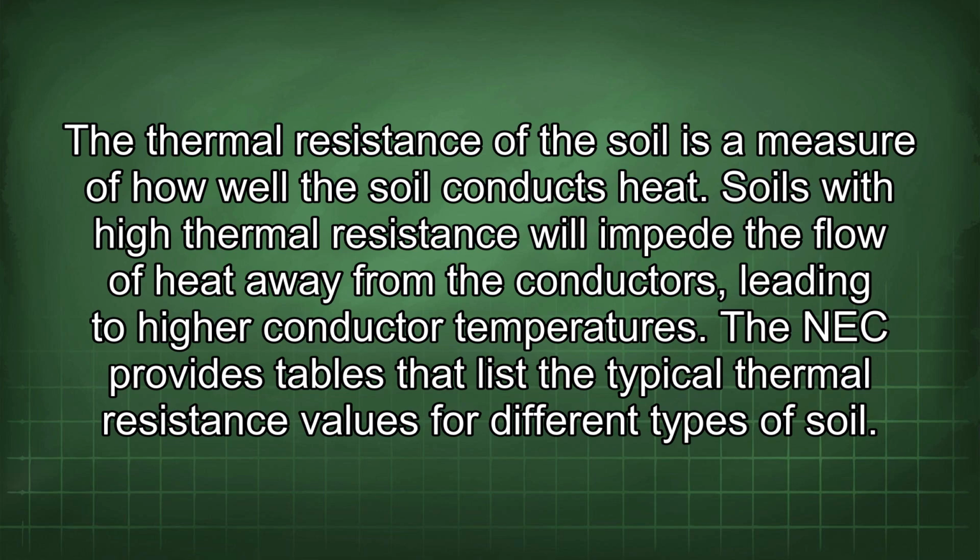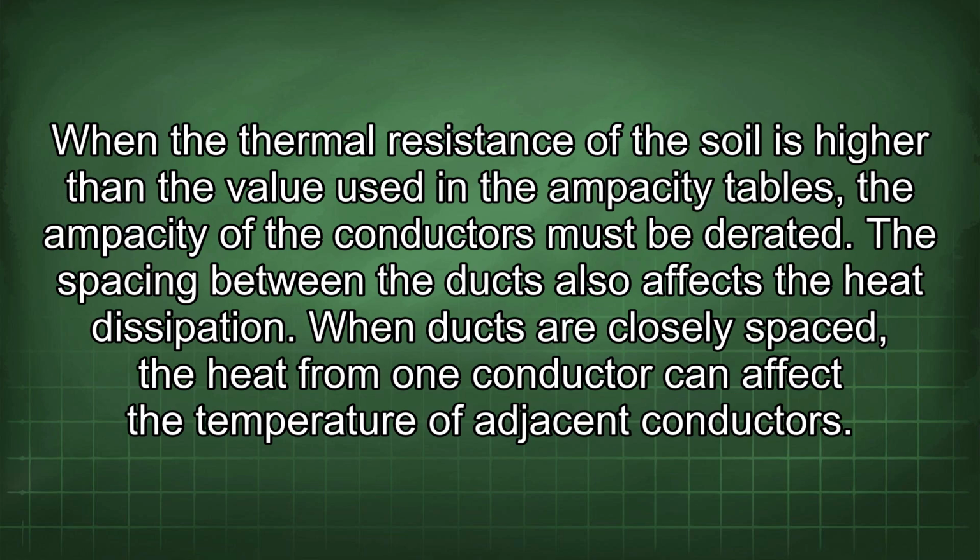The NEC provides tables that list the typical thermal resistance values for different types of soil. When the thermal resistance of the soil is higher than the value used in the ampacity tables, the ampacity of the conductors must be derated.